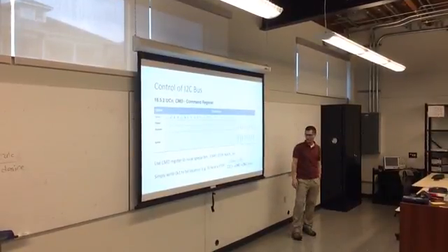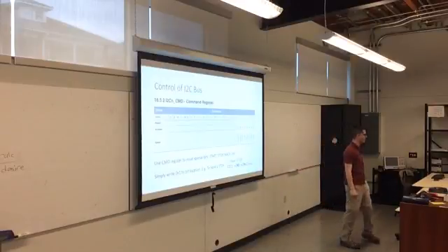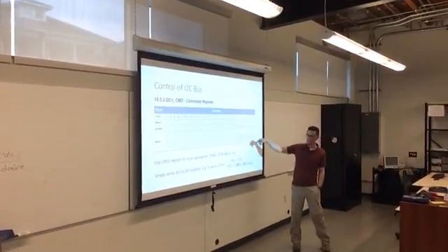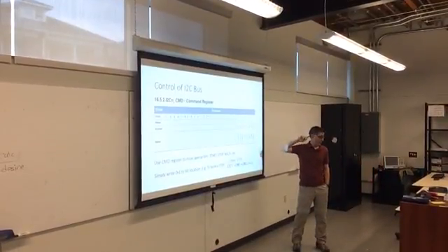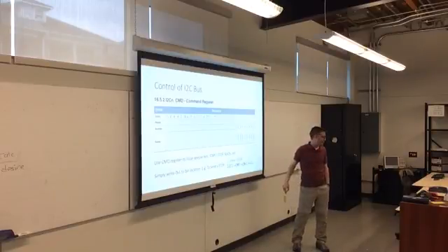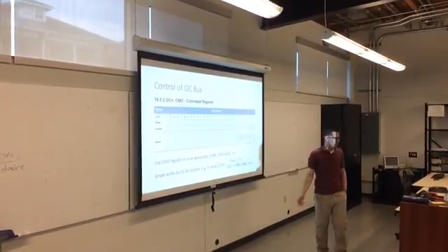So you can imagine that you're going to be doing a couple of these in your code. Everywhere in that box that it says send a start, you want to put a 1 here. And every time that you need to acknowledge, you want to put a 1 here. So you could come up with a little function that's called send start, send stop, send NACK, send ACK, if you wish, and those functions would just be one line of code. Wouldn't be that much to do.